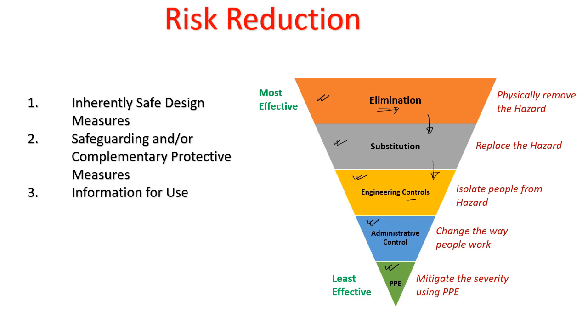The whole acid transportation and pouring can be done through machines, and controls can be kept on the machine so that whenever there is an overflow of the acid, it will cut the inlet valve or feeding valves. That will provide the engineering control.